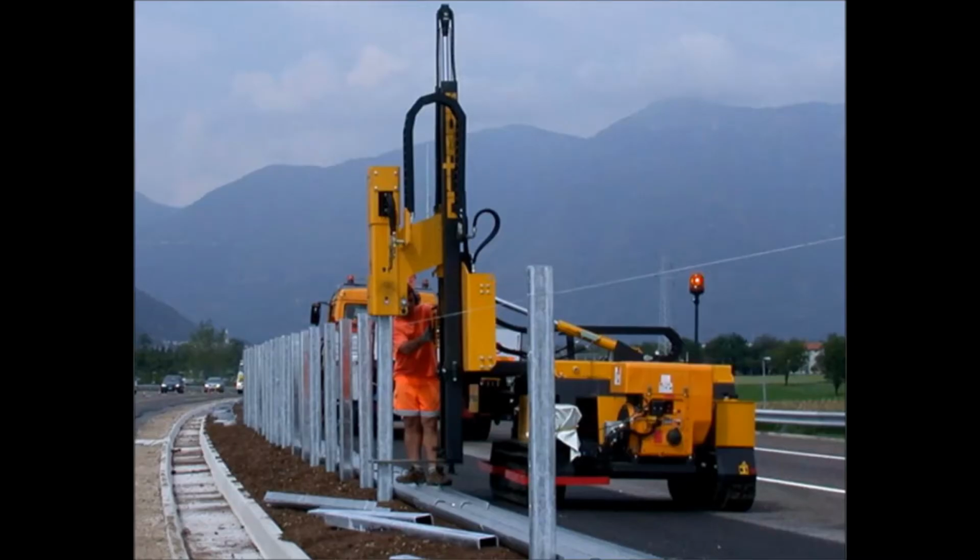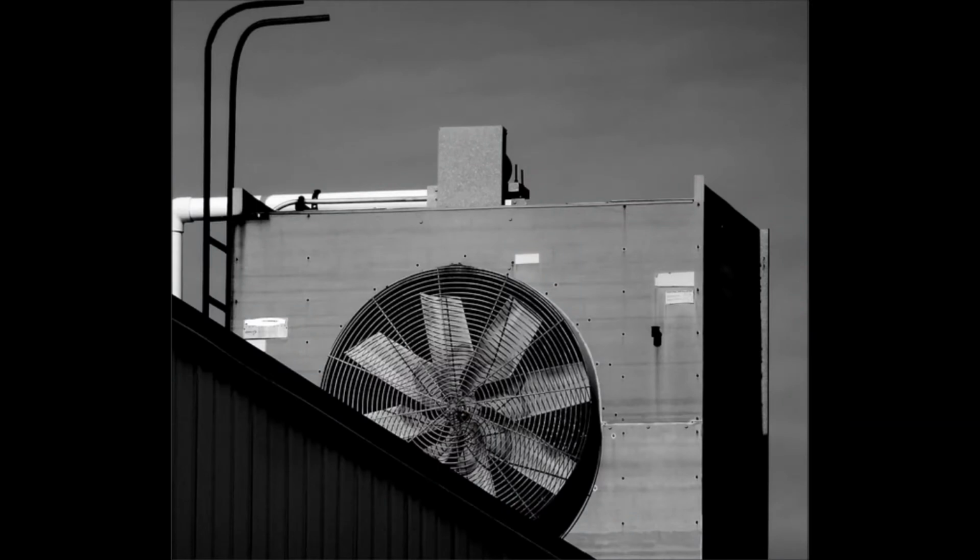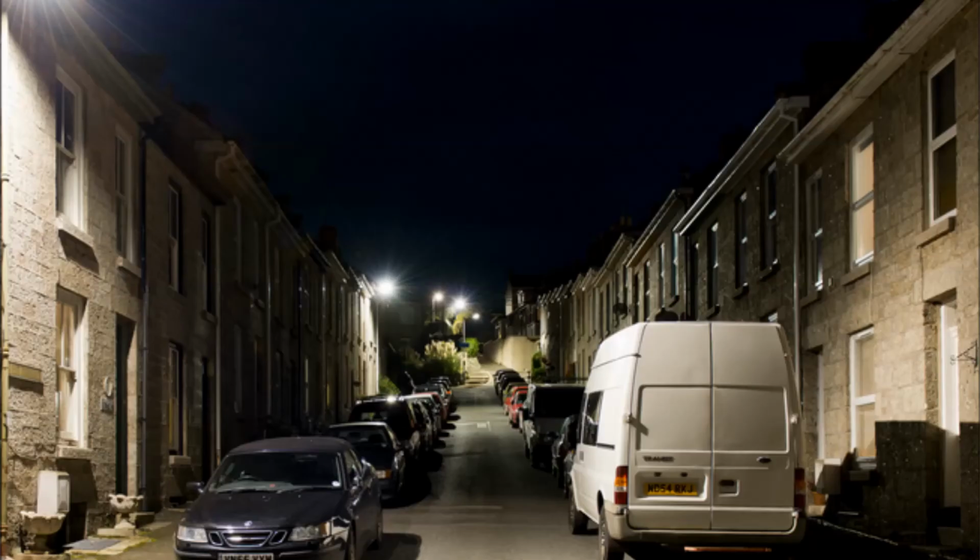Not quite. If there is impulsive noise from the site, e.g. pile driving, a 5 dB penalty has to be added. Or, if there is tonal noise, e.g. from fans, a 5 dB penalty is added. And there is usually a ban on any tonal or impulsive noise at night.